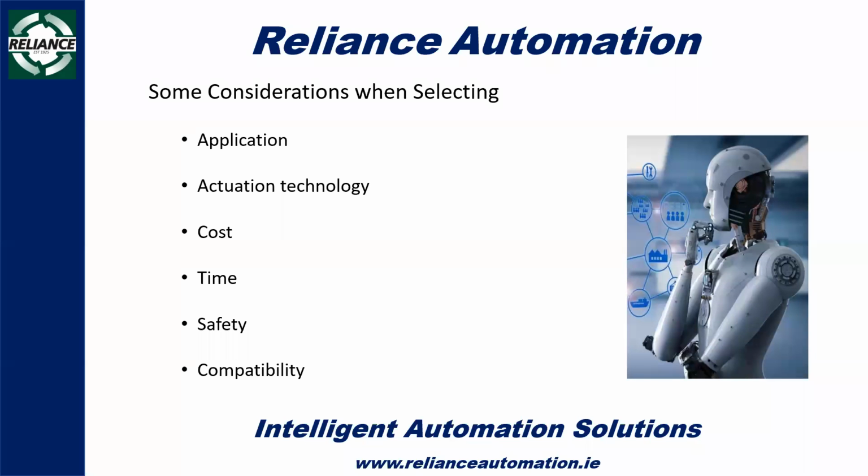So looking at the time then as well, leading on from that downtime piece, is it something that's going to have to be changed an awful lot, or is it something that's going to be fixed in place? And then also the time in terms of your project. Have you got 2 or 3 months to be able to design an end effector that's going to perfectly fit your circumstance? Or is it a case that you've got a project that you've got to get up and running very, very quickly, and you need something that's out of the box, already programmed and very versatile to be able to take on no matter what application you're looking at?